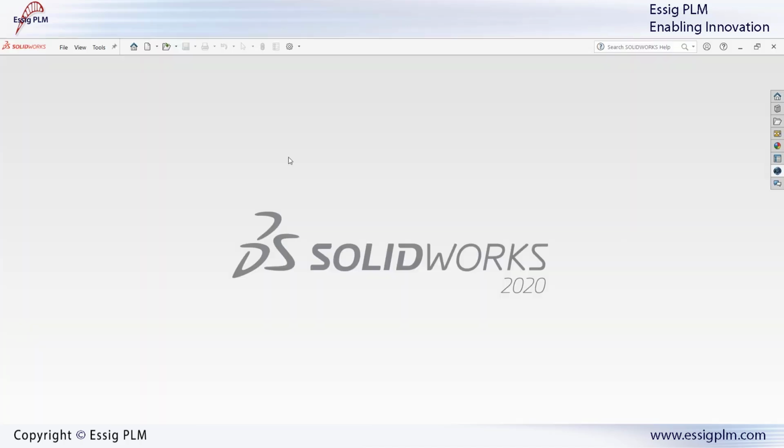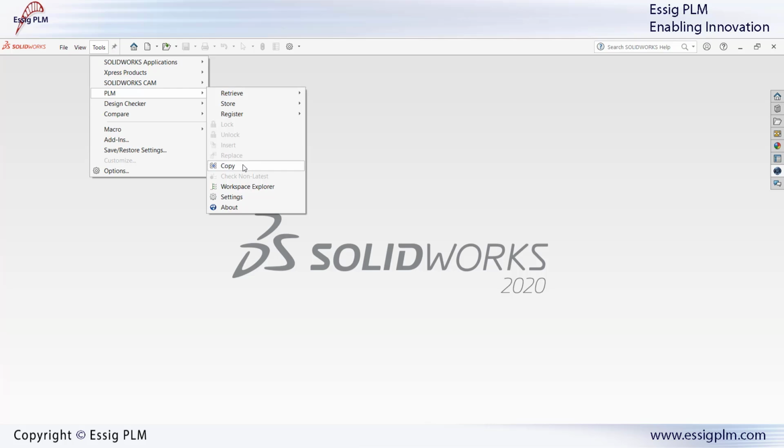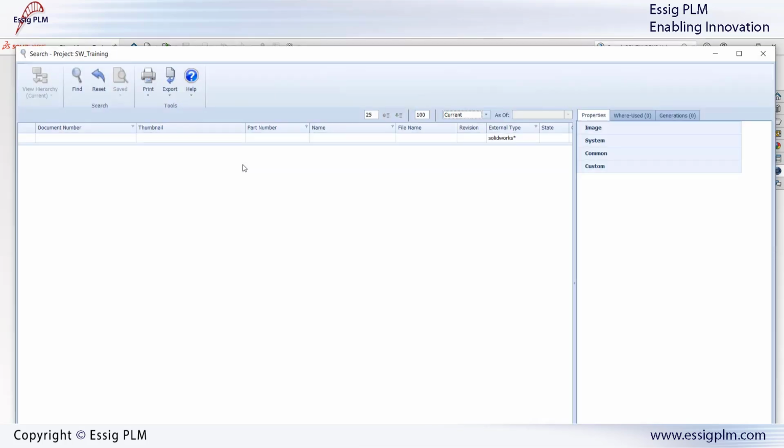To conclude this overview of the SCPLM SolidWorks connector, let's imagine that I need to use that assembly as a starting point for a new design. I just have to click Copy from the connector menu and this opens a search window. Let's search for all Aras CAD documents with MEC in the name.